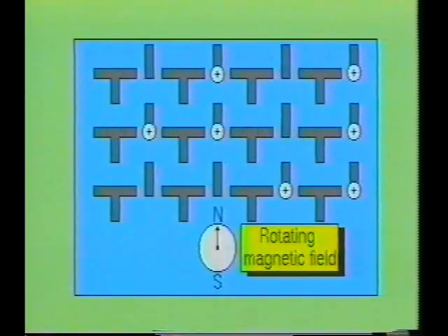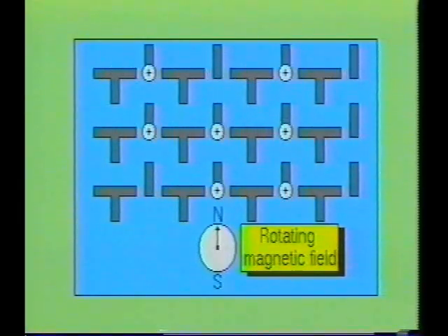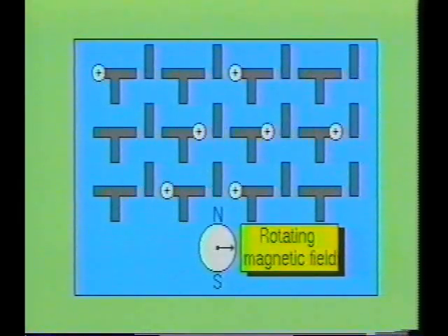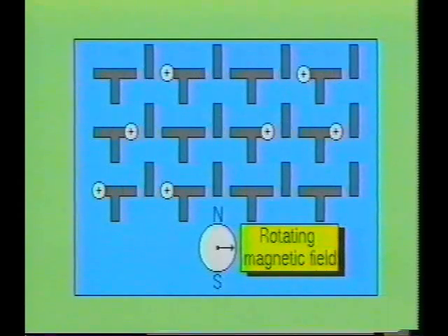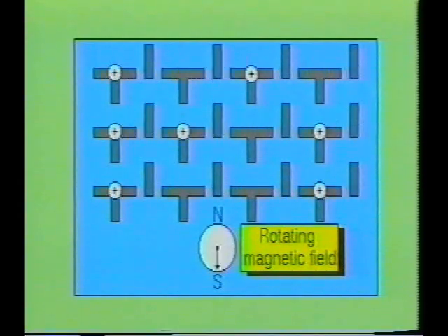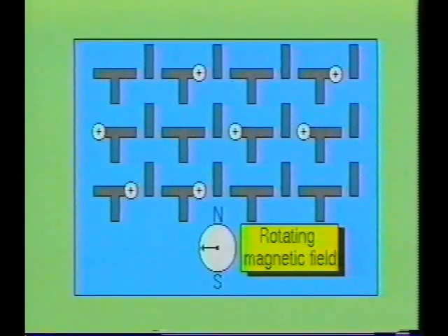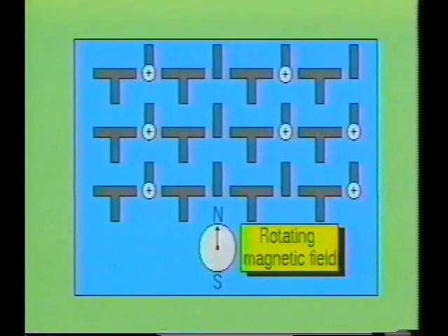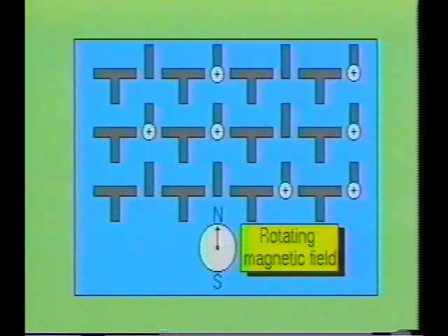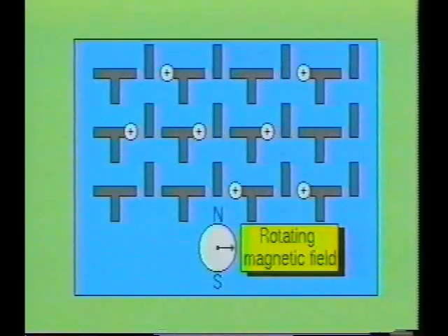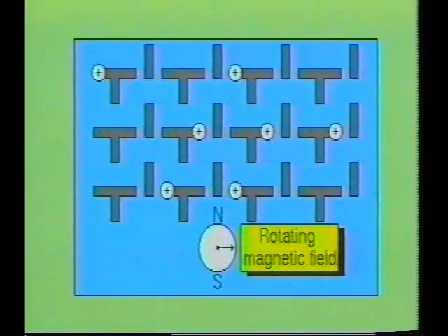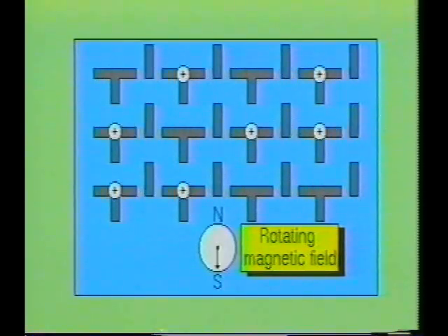As the rotating magnetic field moves, it causes the molecules within the permanent magnetic material to align with the field. Each bubble will move to seek the nearest north pole of a segment. The T-bar configuration will keep the bubbles separated, so there is only 1 bubble per segment. The presence of a bubble indicates a 1, and the absence of a bubble indicates a 0. Each time the field makes 1 complete revolution, all the bubbles will have advanced 1 step.